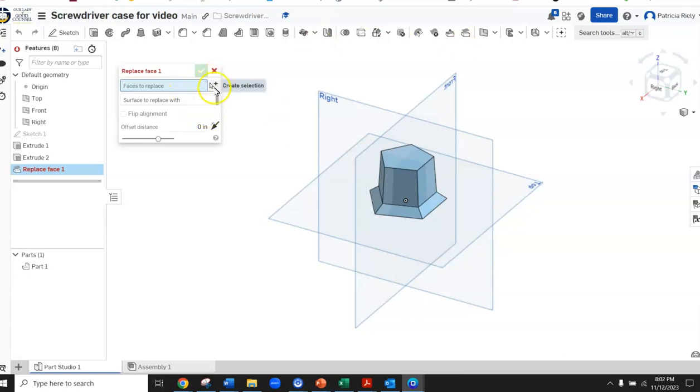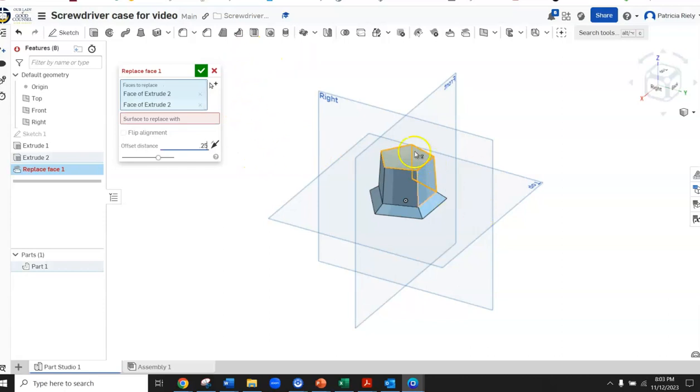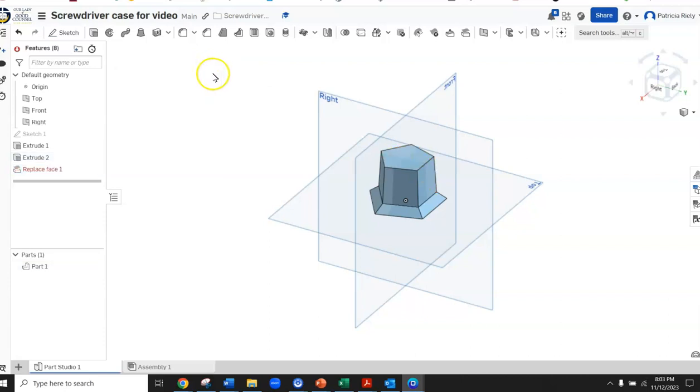So I want a work plane. I want it to offset a distance of 0.25. So this is 0.25. Okay, I don't know if it did that correctly, so let me just see. Okay, I don't like that, so I'm going to go out of there, and I am going to...